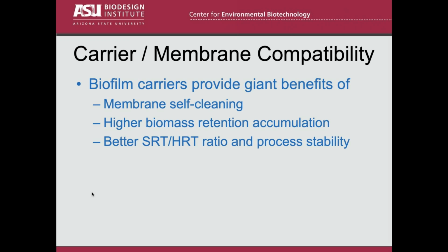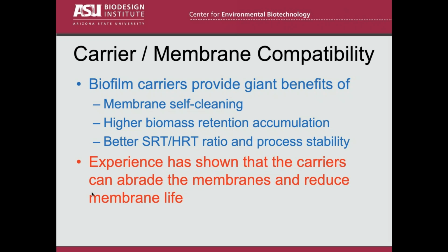So let's start off with the good news. I've already told you this. Putting those biofilm carriers gives us great benefits. Membrane self-cleaning, more biomass retention, better SRT-HRT ratio, all those wonderful things. But, as they say, usually there's no absolutely free lunch. And so what experience has shown is that those carriers, even the granular activated carbon, can over time abrade the membranes and cause damage and reduce the membrane life.